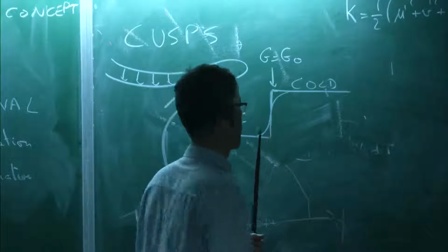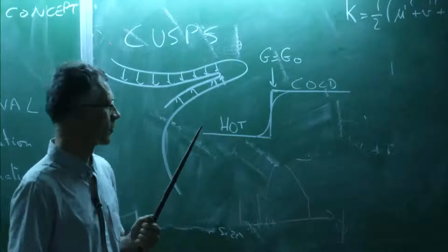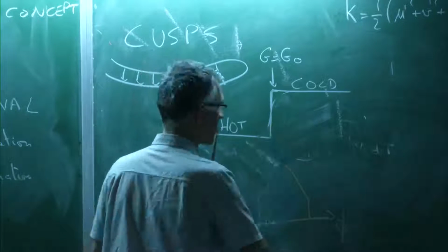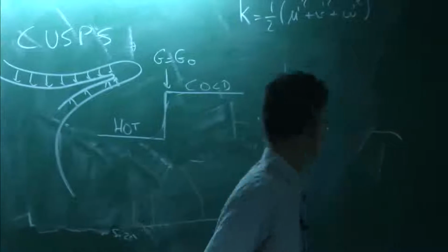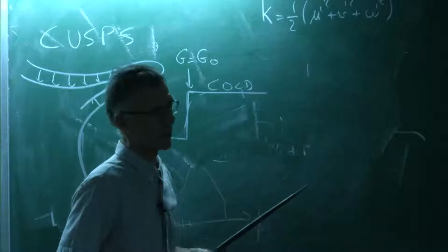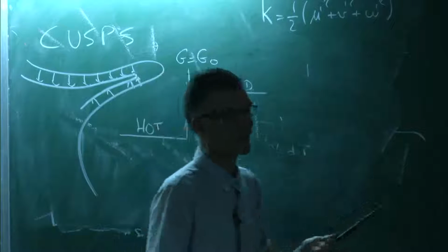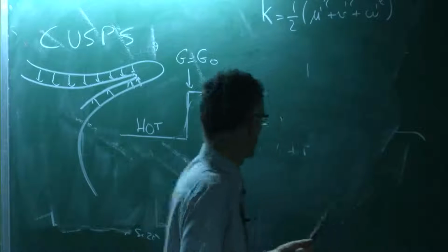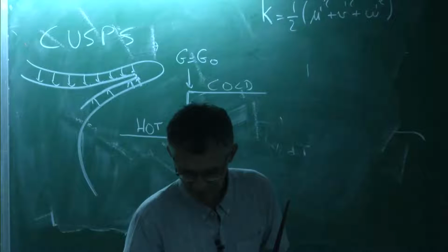Well, that's the point. You talk to Peters or Pitsch, and they tell you we don't do that. We do this, okay? We resolve things on one point. Then you talk to the PhD student, and the PhD student tells you, oh, of course not. We can't. We have to put some second-order term to smooth it, otherwise everything explodes. So in practice, it's not in the papers, but it's in the code. Okay? That's the difference with the second flame model. We start by thickening, and we say it. And then we do the rest. But they don't want to say it. Numerically, it's extremely difficult to resolve a front on 2 points. It's just, especially for density.